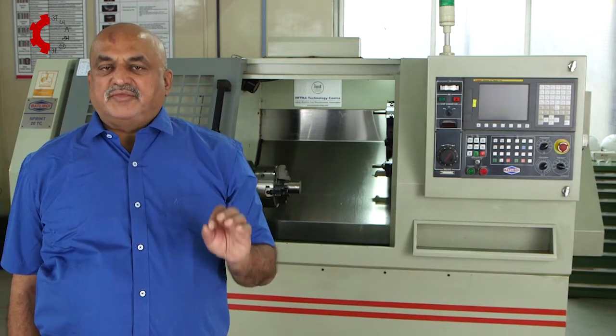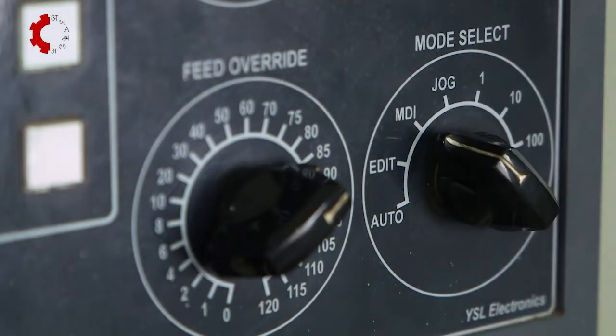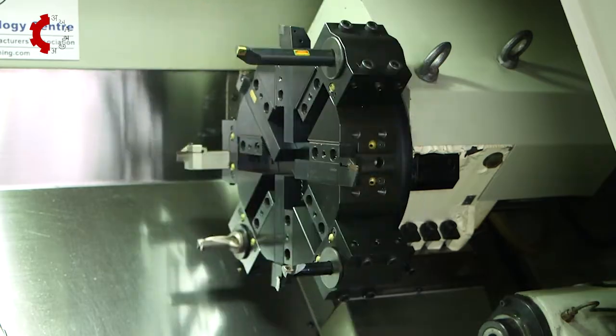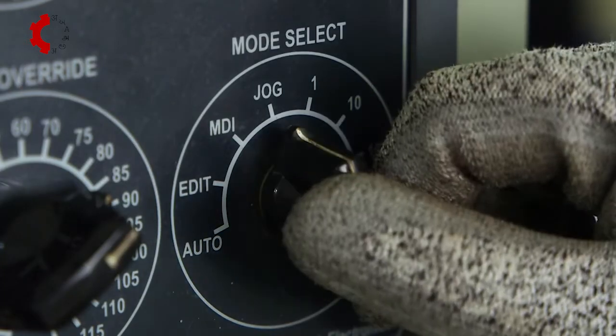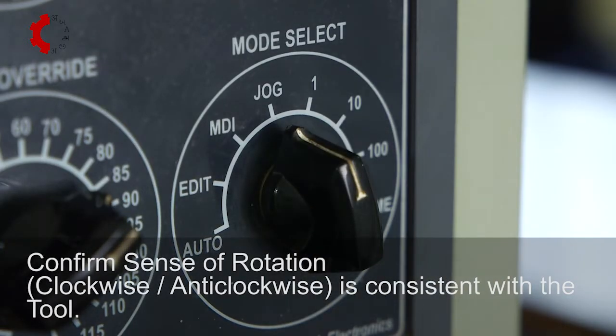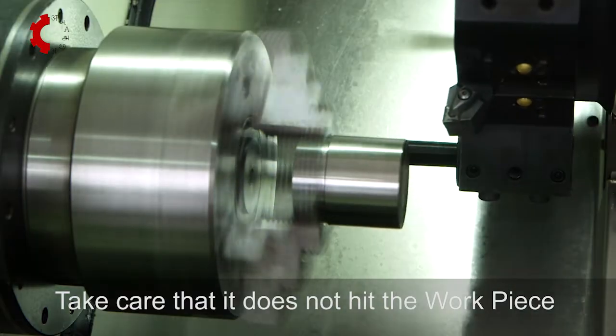Procedure of taking offsets. Select the manual mode MDI. Call the OD turning and facing tool. Give the command to rotate the spindle. Start the spindle. Switch to jog mode. If the spindle stops, start it again by using the spindle revolution button on the control panel. Bring the tool near to the workpiece.